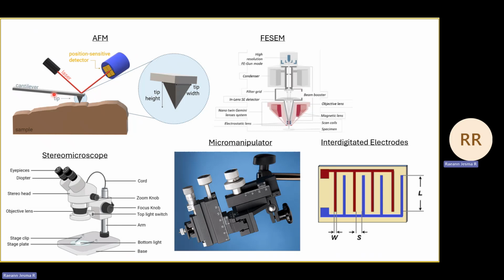There are many applications for AFM. One of them is surface mapping. It means you can find out the profile, what kind of terrain the surface of a sample has, and so on. You can also manipulate a sample. This cantilever is generally actuated by using a piezo actuation scheme. It will be made to contact by applying a suitable amount of piezo voltage. You can make the cantilever apply a suitable amount of force on the sample.